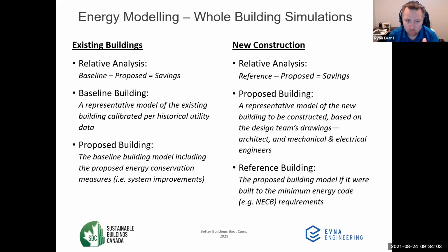Once we've created our proposed building, it's from the proposed building that we go and create the reference building. So that's the key difference in new construction versus existing building. In an existing building, we have our baseline that's representative of our building with historical data, and then we go and create our proposed building from that baseline. It's the inverse in new construction.